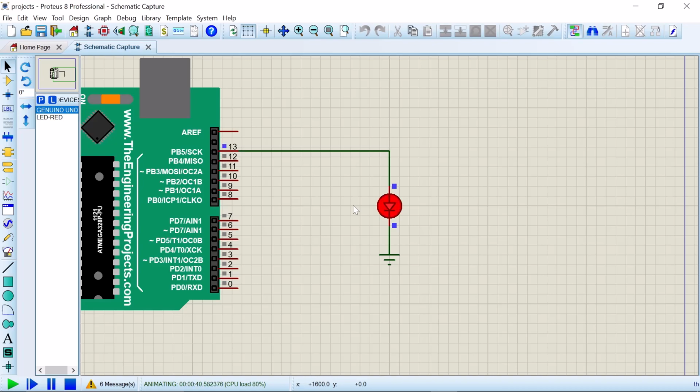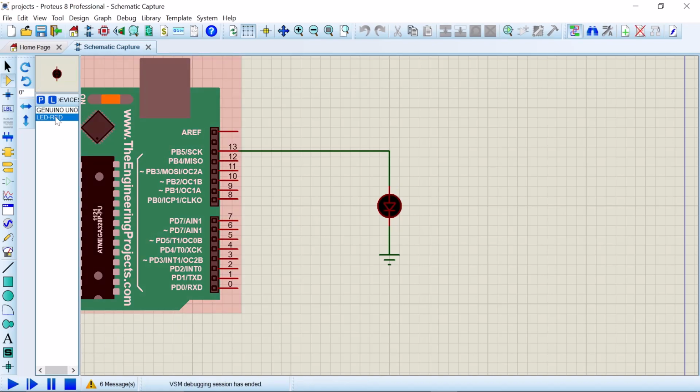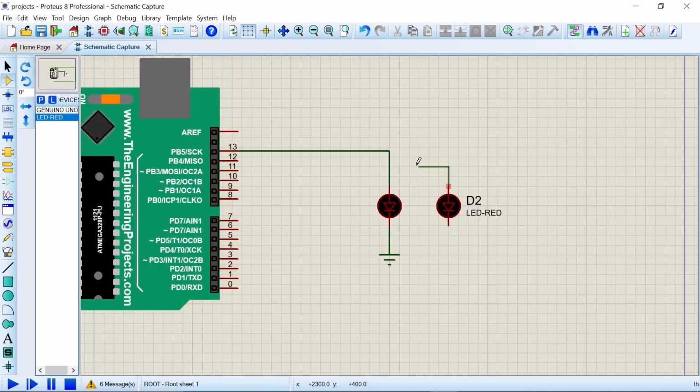So today we want to just play a little bit around this whole thing. That is, we want to fix another LED and instruct ChatGPT to blink these LEDs for us. So in that case, let us stop this. Come to the LED, put it here. We can connect this to pin 12. Then this one has to be connected to ground. Since they are both connected to ground, they can share a common ground.